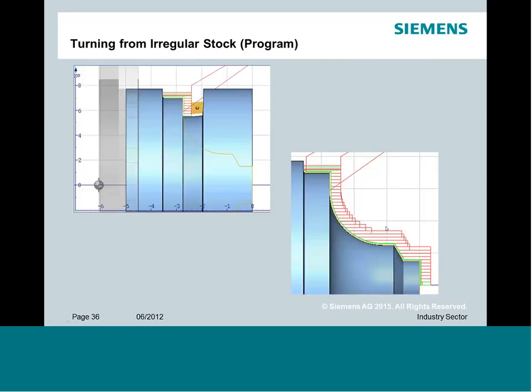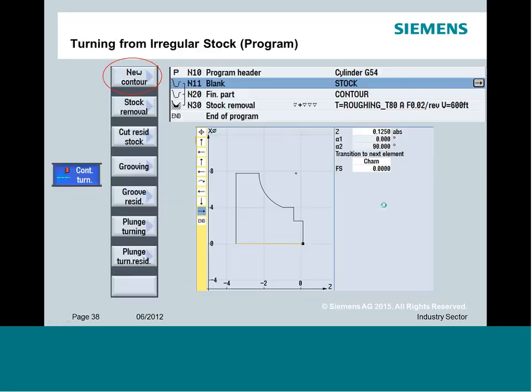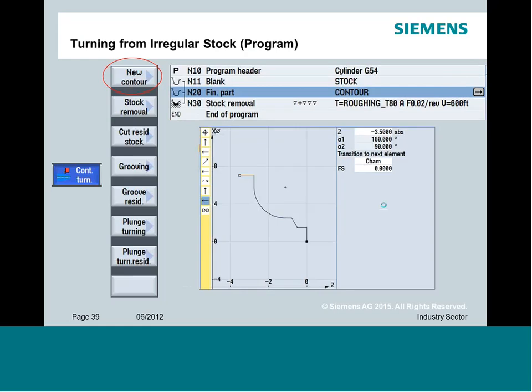And what allowance will do is it'll say, okay, I'm going to put that amount of material on the entire shape and just machine those areas like we see here. Just going to kind of run down and just machine those areas. After that, we're then going to explore drawing the irregular stock and how that all kind of links together. And we'll build that in. We'll have our finished part as we did before.